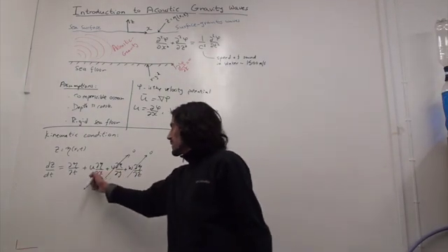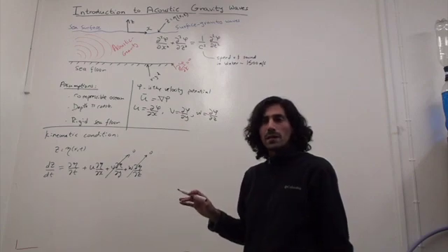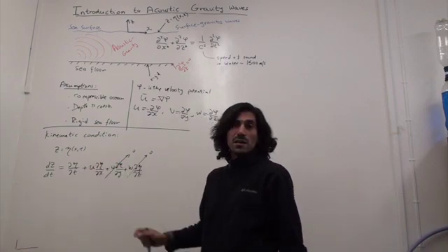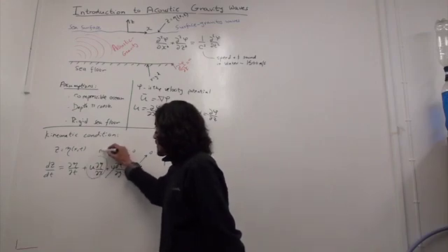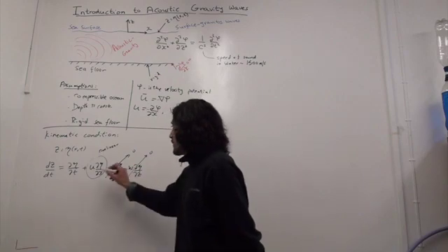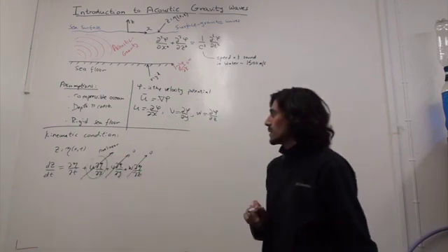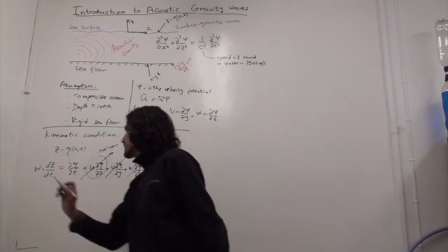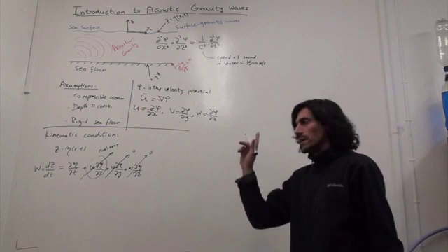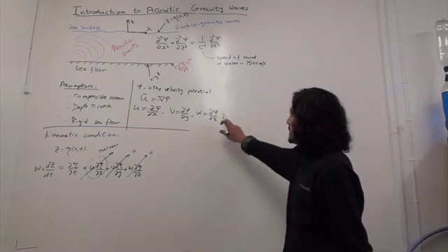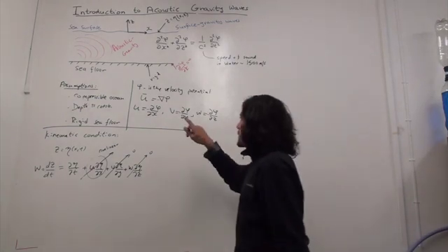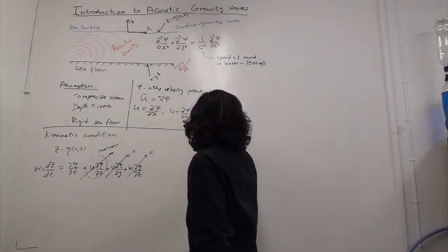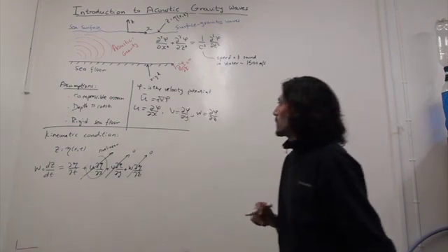But in addition, we are solving only linear problems. We are not looking at non-linear terms, and this term is non-linear. You see, you have u times d eta dx. This is a non-linear term, and therefore we also neglect it. So the condition is, and what is this? This is the velocity, right? dz dt is the velocity in the z direction, which is basically d phi dz. So not to confuse you, let's say we choose plus. You can just put a plus also if you want. We have to be consistent, so it's a plus everywhere.